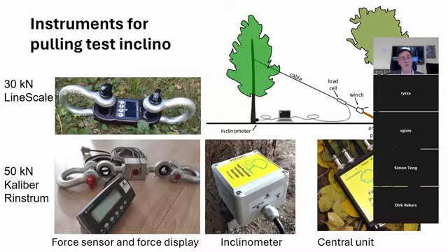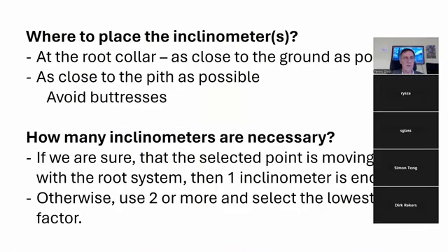The other very important sensor is the inclinometer. This inclinometer sensitivity is pretty high, 0.001 degree, and when we have more inclinometers, let's say 2, or in the case of 3 instruments, data is collected by the central unit and transferred to the laptop, a Windows-based laptop.